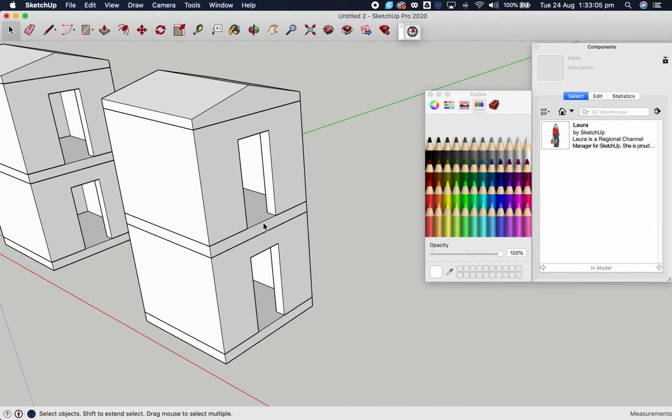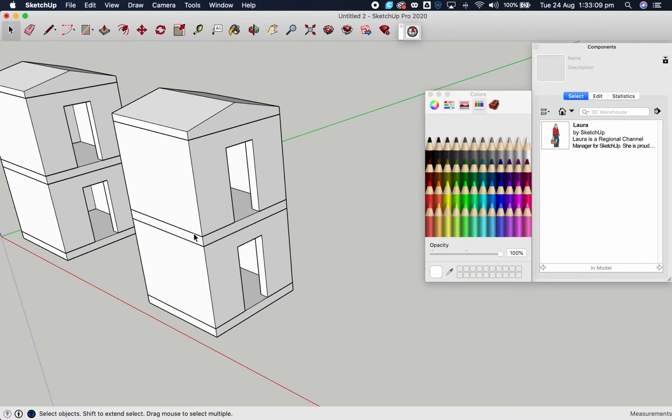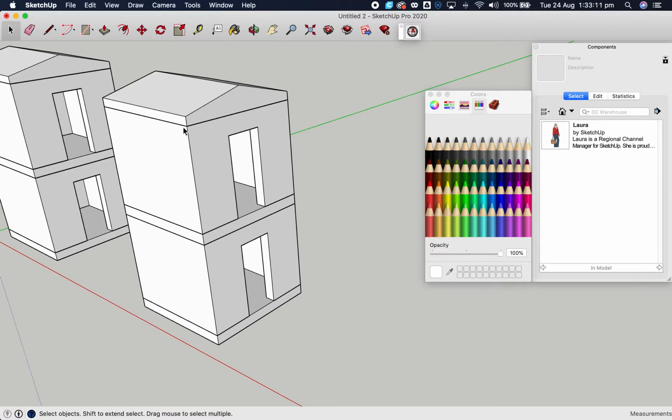Okay, so the best method here is that when you do print, a printer cannot print a floor above a surface, right? So this item here would be all filled in with a lot of other plastic as the second color, for example, or PVA. I don't recommend using PVA because it's very finicky. You'll have a lot of failed prints. Okay, so that's for those who are using a 2-color printer.